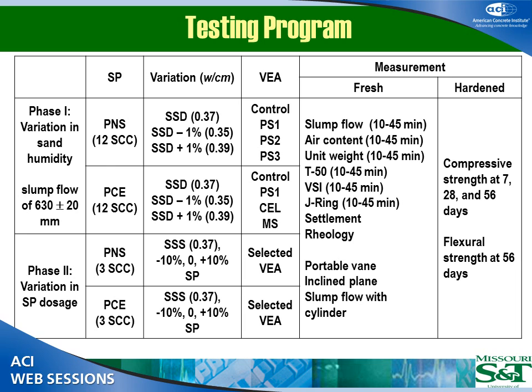And we also looked at thixotropy using a couple of test methods, portable vane and inclined plane, to allow us to look at the rate of increase in static yield stress with time. And also mechanical properties, both flexure and compressive strengths, up to 56 days.